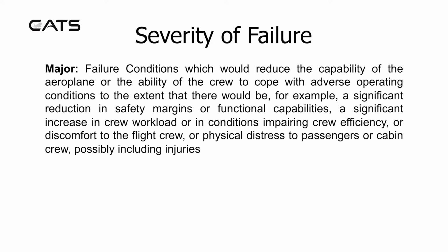Major are failure conditions which would reduce the capability of the aeroplane or the ability of the crew to cope with adverse operating conditions, to the extent that there would be, for example, a significant reduction in safety margins or functional capabilities, a significant increase in crew workload or in conditions impairing crew efficiency or discomfort to the flight crew, or physical distress to passengers or cabin crew, possibly including injuries.